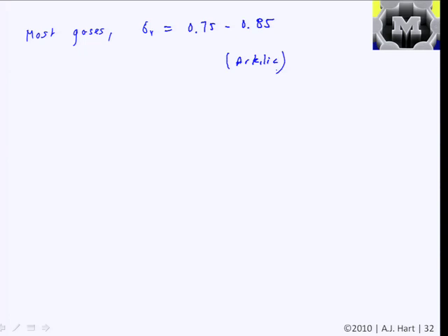And they actually describe, as we'll see in a minute, how they characterize the slip flow through microchannels and make such high precision measurements that they're able to calculate what this actually is. And so you can look into sources and look this up for various gases, but if you're doing this kind of calculation, a value of about 0.8 is pretty accurate.